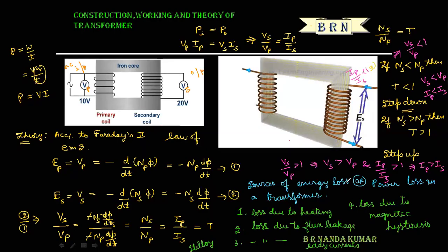What is the meaning of transformer? A transformer is a device used to vary the AC voltages and hence AC currents. A transformer works on the principle of mutual induction. A transformer is of two types, step up and step down. A step up transformer increases the alternating voltage by decreasing the alternating current. A step down transformer decreases the alternating voltage by increasing the alternating current.